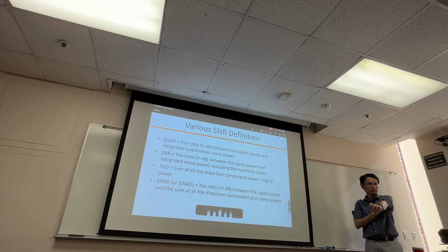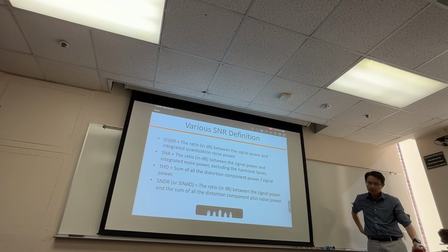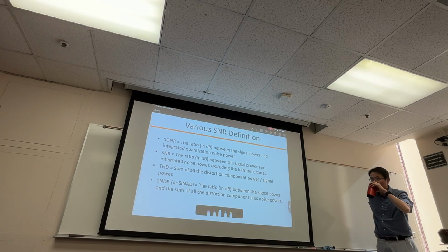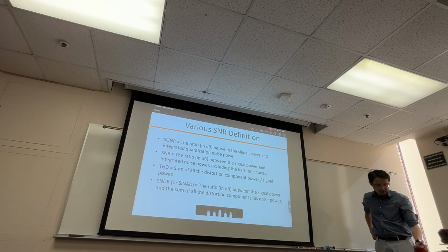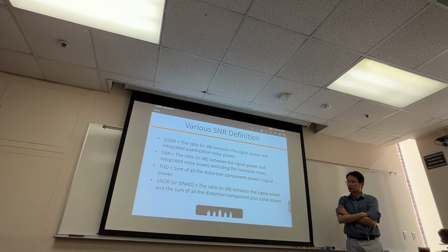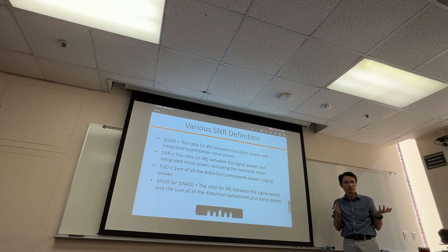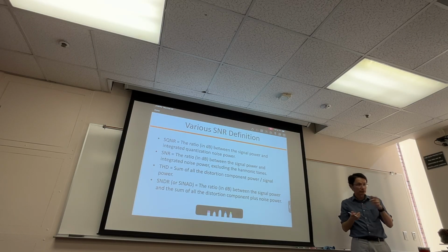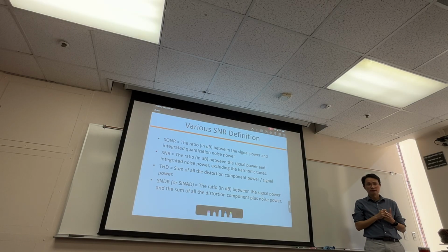Why does SNR matter if at the end in reality the SNDR is what matters? Very good question. He's basically saying that SNDR includes everything, right? So it looks like everybody should only care about that number, but not the SNR. Very good question. It turns out that in some applications, they can tolerate the distortion, but they cannot tolerate the noise floor.